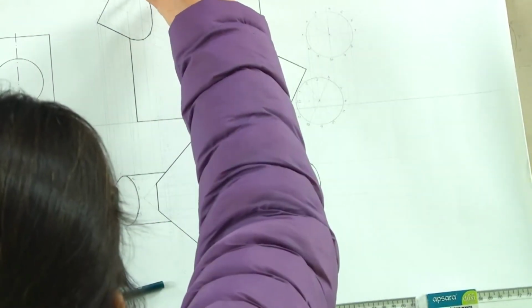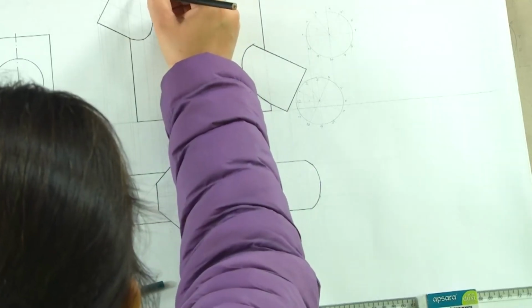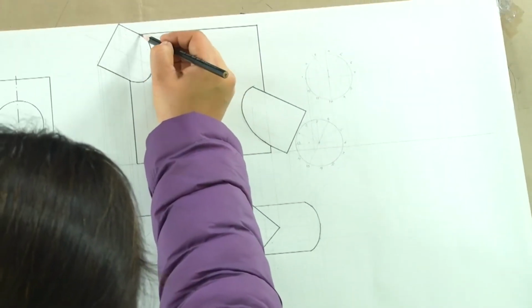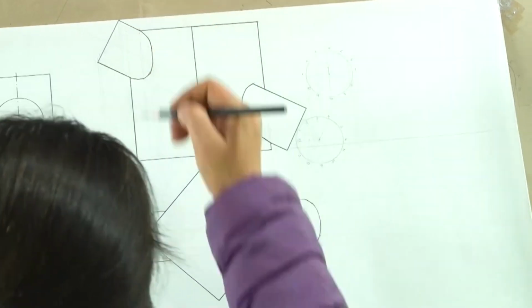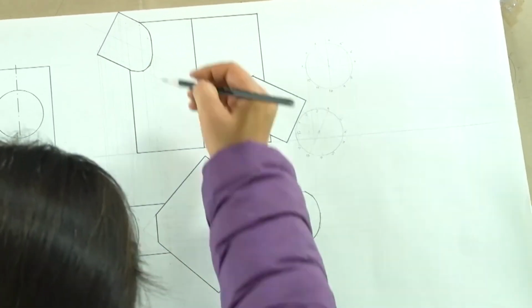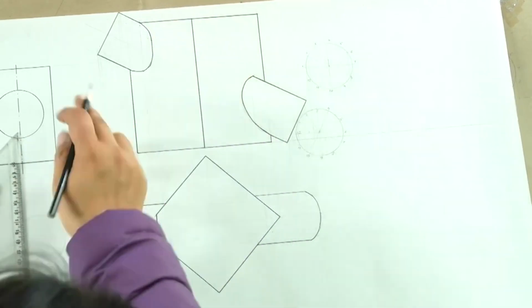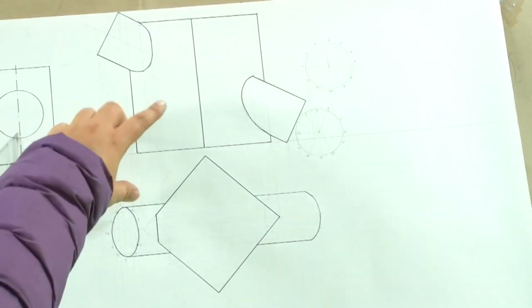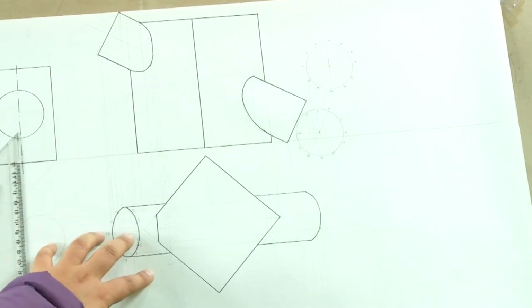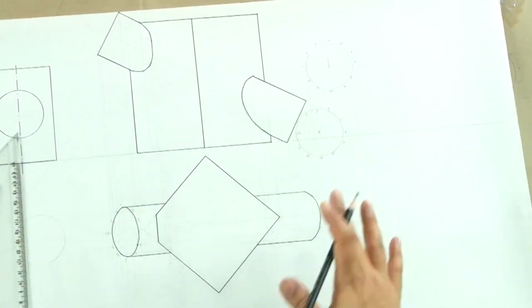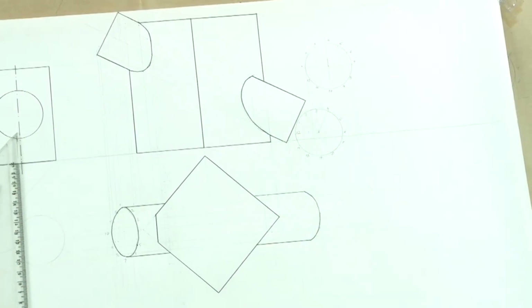So, which is what we got here. Otherwise, we should have actually got the point somewhere here. Since it was cutting it, it was abrupt, and that is why we got a straight line, and from there the rest of the elliptical, the curvilinear surface would start. So, that is how the cylinder would look when we see it from the top and from the front. That is how the orthographic projection of this intersection is going to come.